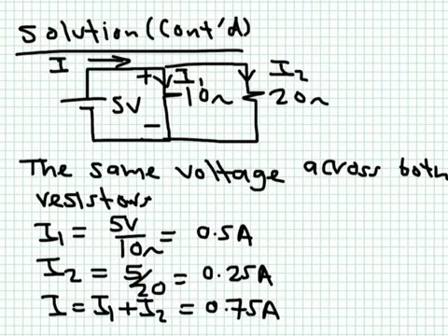And as we'll see later from Kirchhoff's current law, the current flowing into this node is equal to the currents flowing out from that node. So the current I, the total current drawn from the battery, is equal to I1 plus I2. So it's equal to 0.5 plus 0.25, or the answer is simply 0.75 amperes. Actually, all currents are in amperes, all resistors are in ohms.